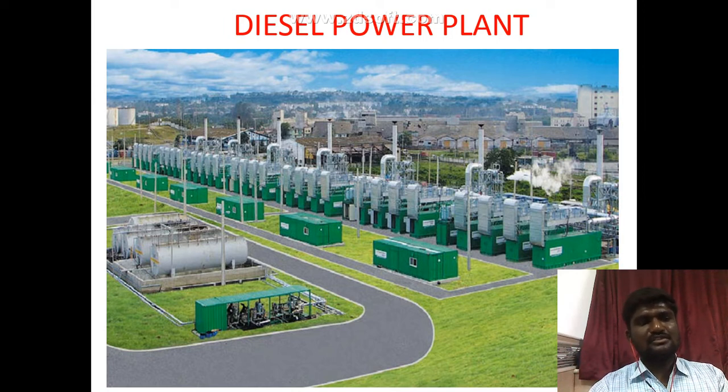So the cycle can usually be represented on the PV and TS diagram, and the following assumptions are made in the analysis of a gas power cycle. First, the working medium is a perfect gas throughout the system. We have to follow the gas law, PV equals m R T, where P is the pressure, V is the volume, m is the mass, R is the gas constant, and T is the temperature.